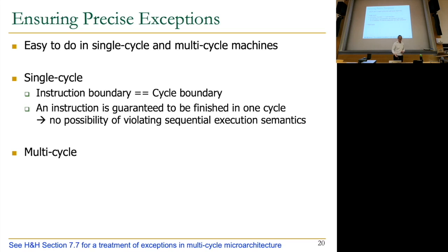An instruction is guaranteed to be finished in one cycle, so there's no possibility of violating sequential execution semantics. Because one instruction is finished, the other instruction doesn't get started before the previous instruction finished. So there's no problem here.